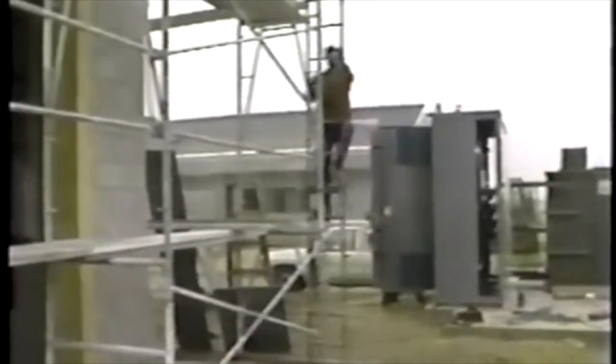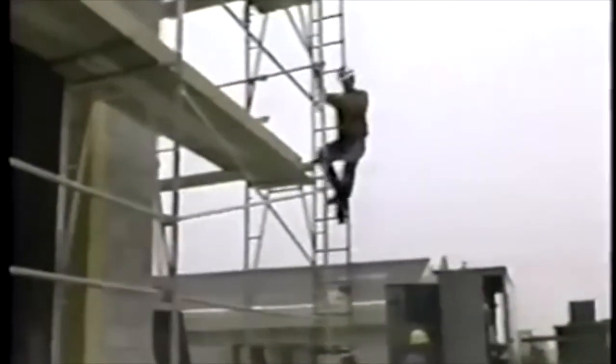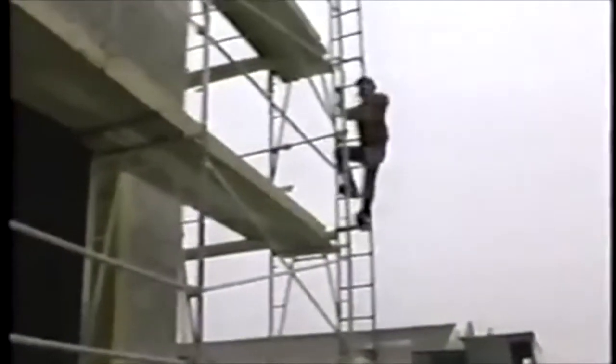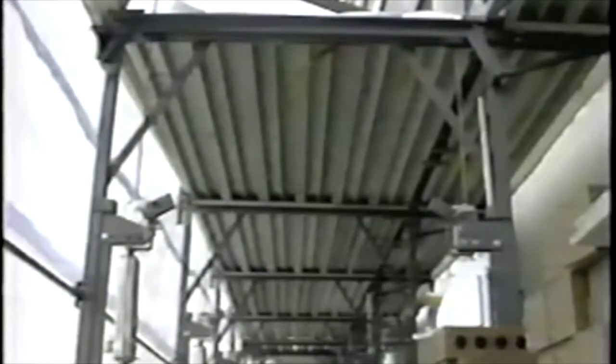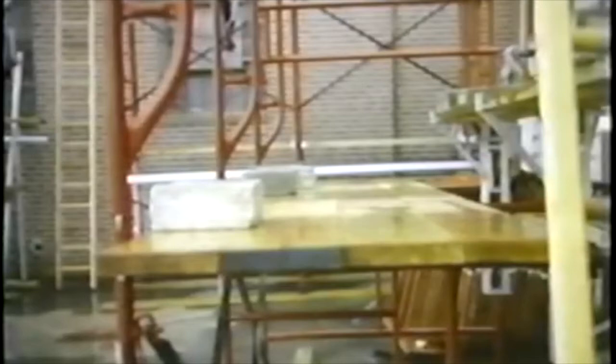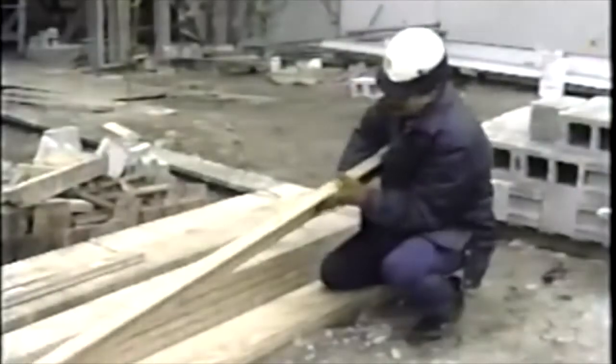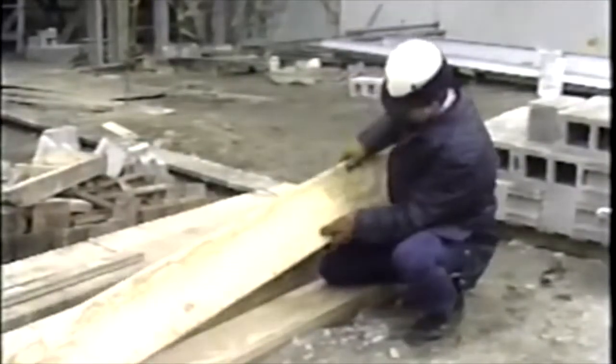Also note whether an access ladder or equivalent means of safely getting onto and off of a scaffold is provided. Ideally, scaffold planks should be metal, usually aluminum. When wood is used, however, the planks must be scaffold grade or the equivalent. That means the specific classifications of strength as determined by either the West Coast Lumber Inspection Bureau or the Southern Pine Inspection Bureau. The classifications are marked on each plank.